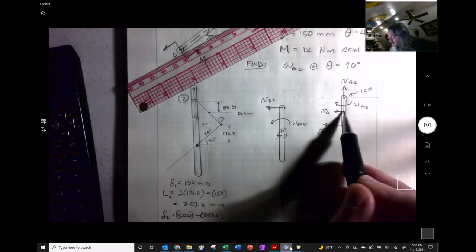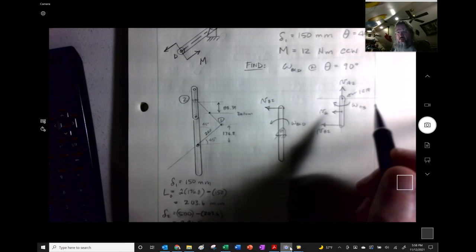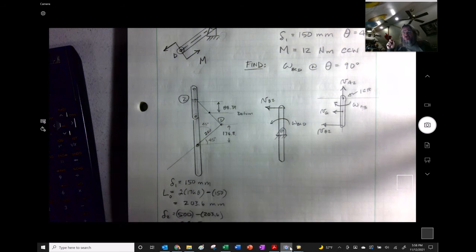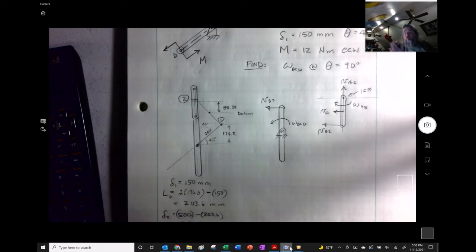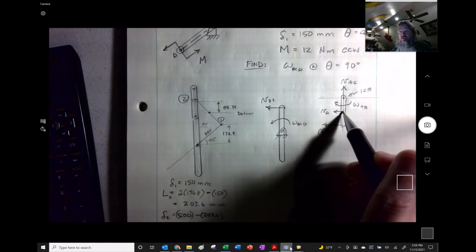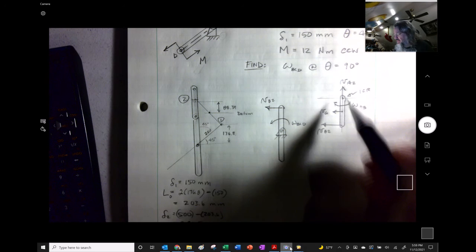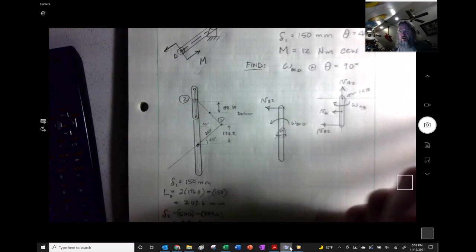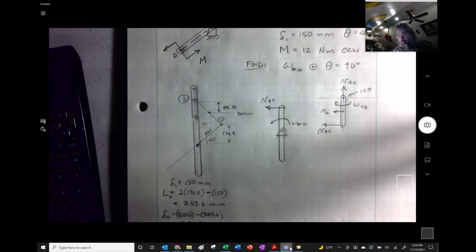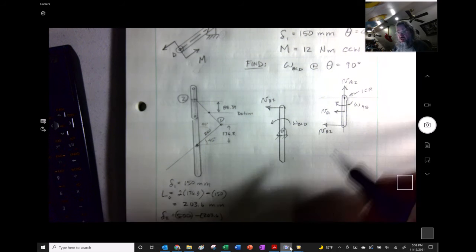But what we have to care about is the motion of the center of this, because this is not a fixed piece. It's not flying through the air, but it's translating and rotating, whereas this guy is just rotating because it has a fixed point. This thing is actually moving. The center of it has a velocity. So at the instantaneous center, it looks like it's traveling about there. I'm just trying to be careful. It's fortunate; we probably could get away with making a mistake and it not counting against us if we just took it as pinned about this one spot. But let's take it right around here.